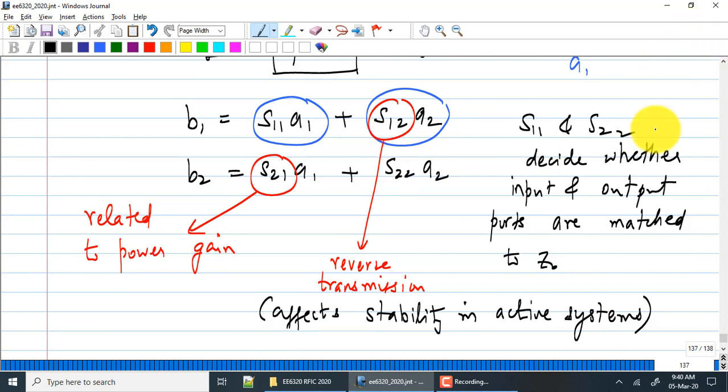The reason is you have explicitly made the LNAs unilateral, right? By adding cascodes, etc. And that normally works quite well. In the case of power amplifiers, the devices are so large that S12 will be very small. If you measure S12 for LNAs at these frequencies, you should normally not have a big problem with stability.